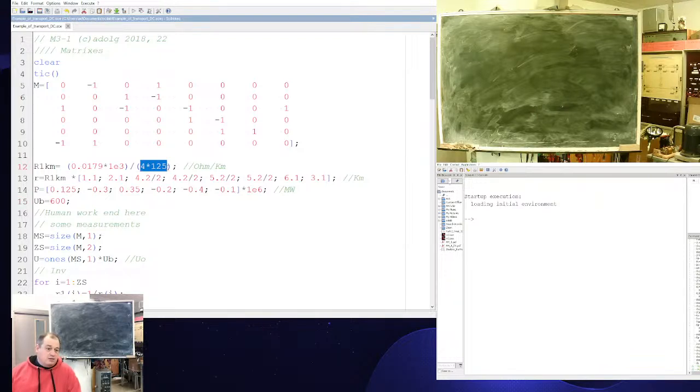In parallel, 4 by 125 square millimeters. It's an old tram wire put in two on each direction and with joints. It's very typical for our city, with a forward line, a backward line, joints between them, and power from underground cable.